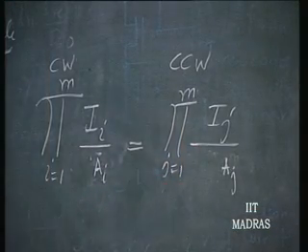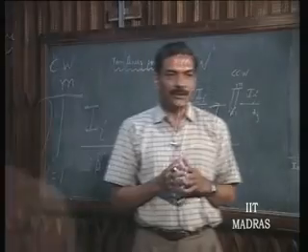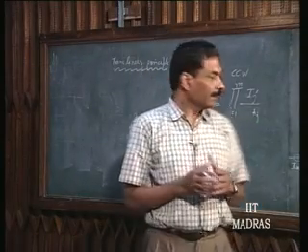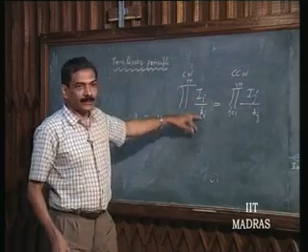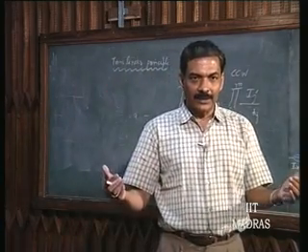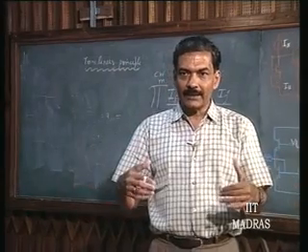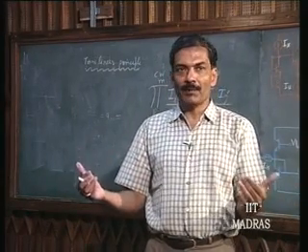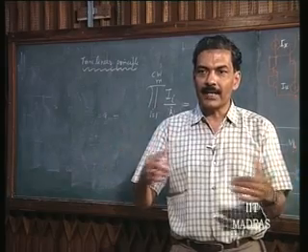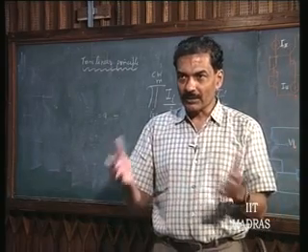And this is the most generalized translinear principle relationship: the product of current densities of those transistors or diodes connected in the clockwise direction shall be equal to the product of current densities of those transistors or diodes connected in the anti-clockwise, counterclockwise direction.